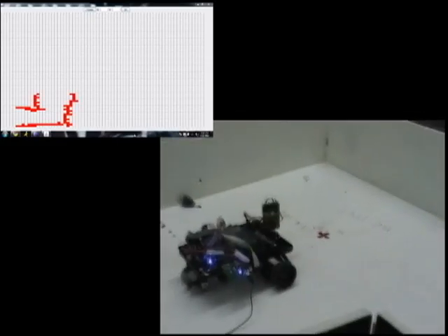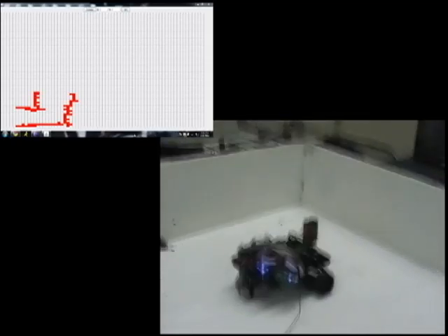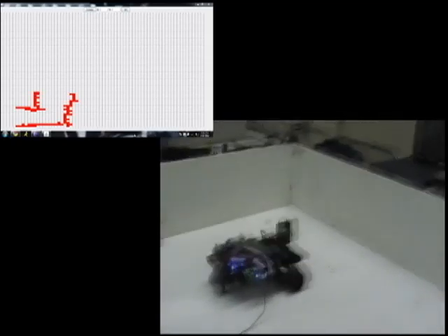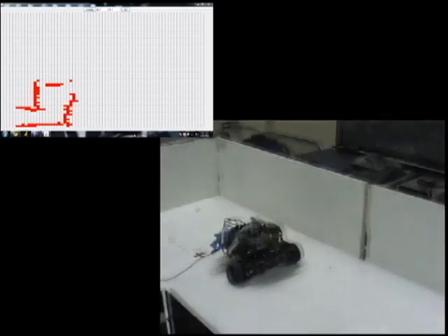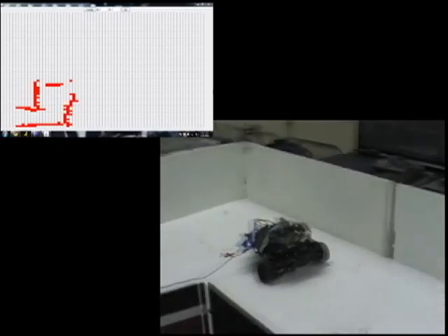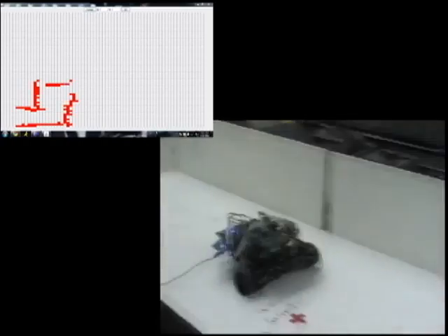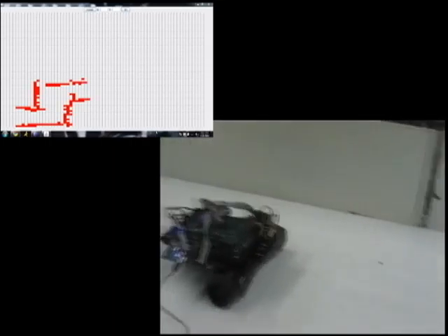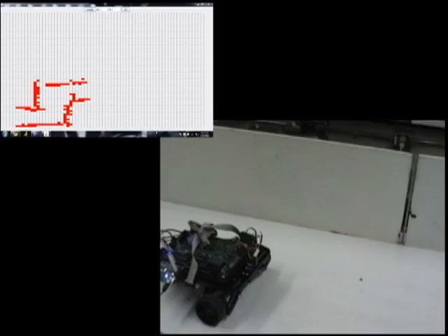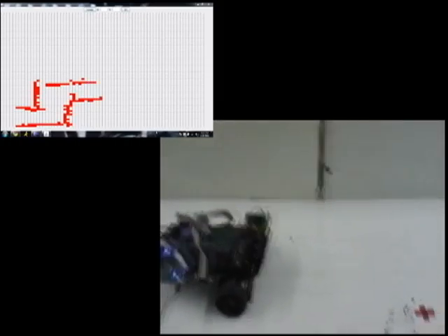And the robot is avoiding the obstacles, the walls, and going towards the waypoints, which you can see on the field, are marked with the red X's, and it continues on its path planned by the wavefront algorithm. The wavefront algorithm is run every 3 steps. When you see the sensor sweep, it sweeps the sensor, runs the wavefront, and then sends the information to the computer via the serial cable, updates the GUI, and then drives the next 3 spaces and repeats the same process.